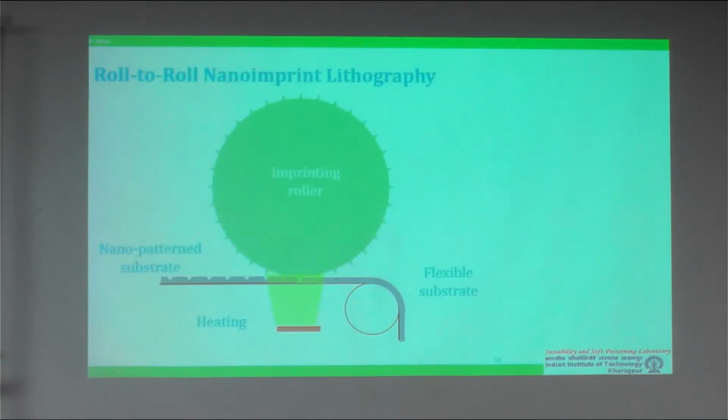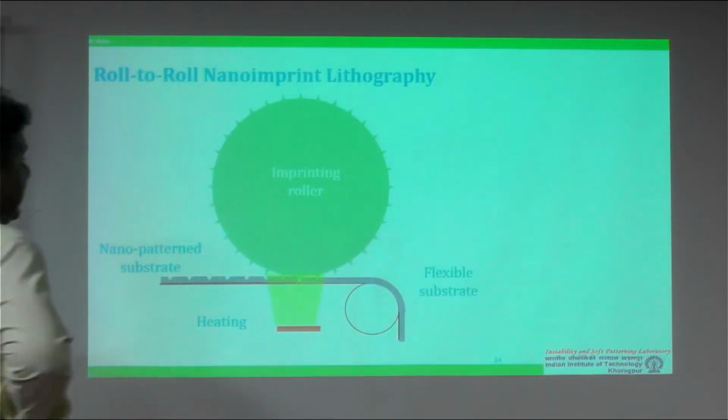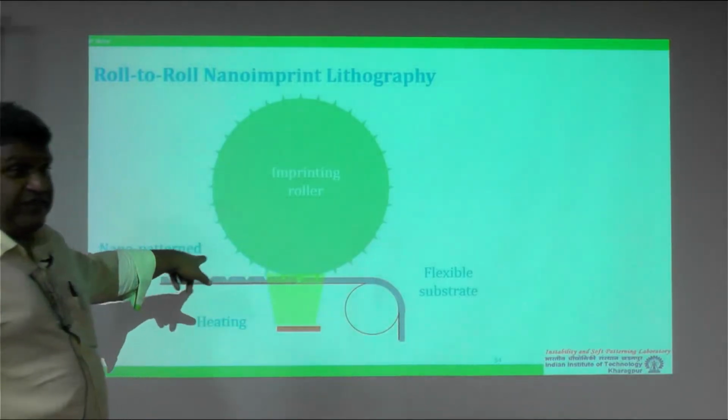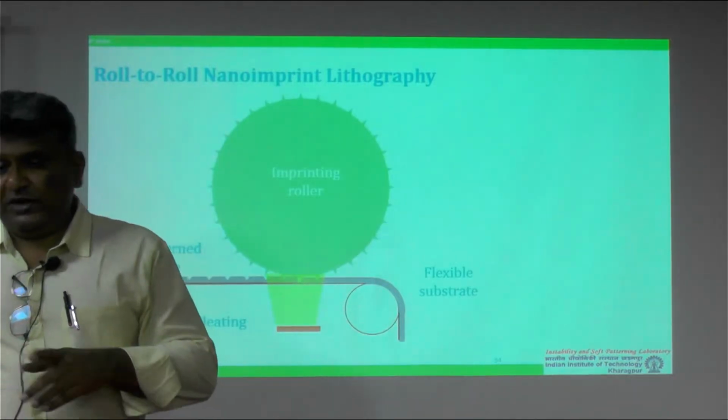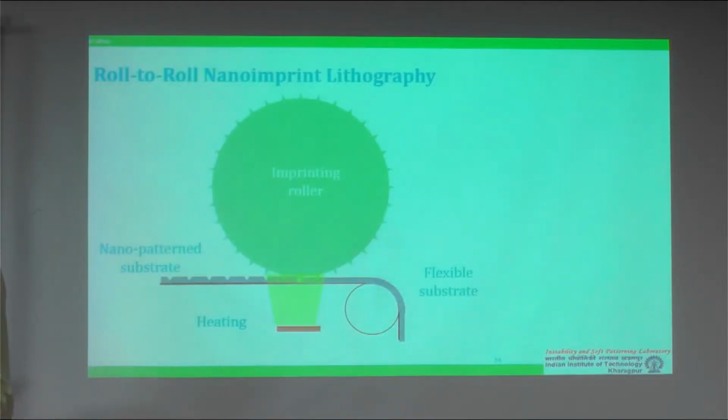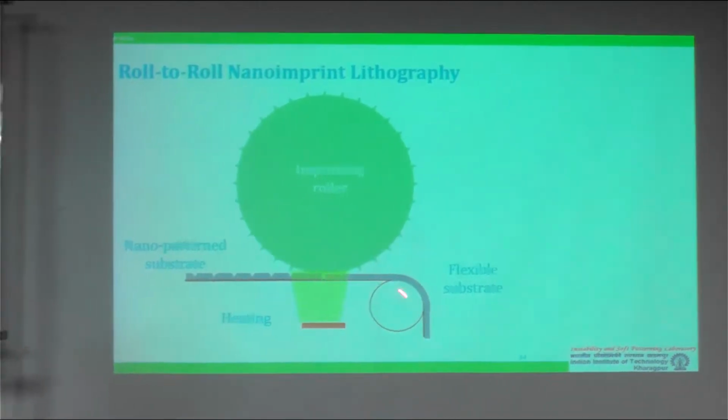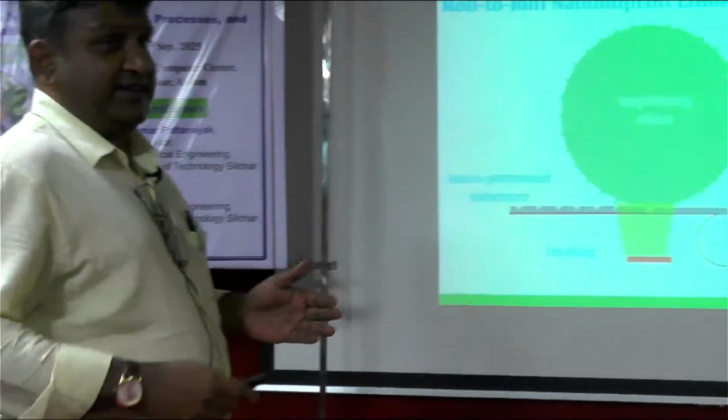And that led to the development of what is known as roller nanoimprint lithography. There is a lot of beautiful science involved here. It is limited; you cannot apply it everywhere. If you have a flexible substrate over which the polymeric material is coated, you can transform it for a roll-to-roll process. But what needs to be done? You have a glassy polymer coated on another flexible substrate, let's say a transparency sheet.